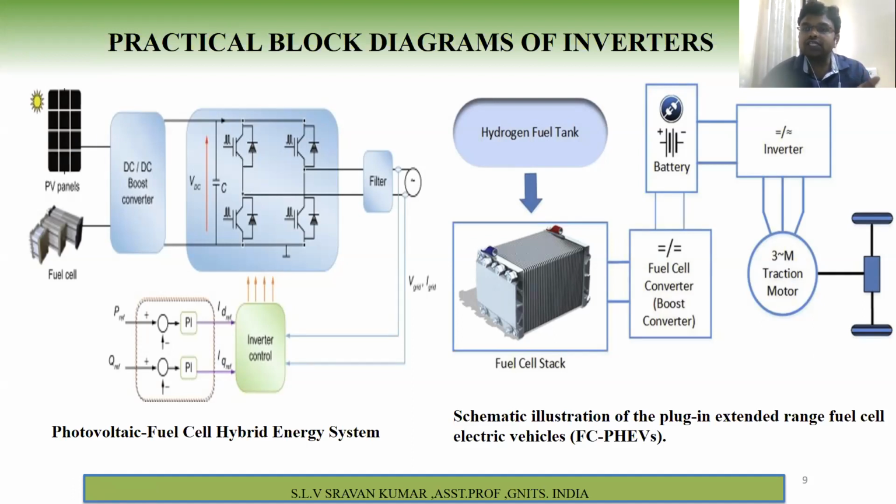Firstly, we have to convert AC to DC, and again we have to convert DC to AC to control the load, because wind will generate AC, which we cannot directly connect to the load. So after wind energy, we use AC to DC, again DC to AC, like that.